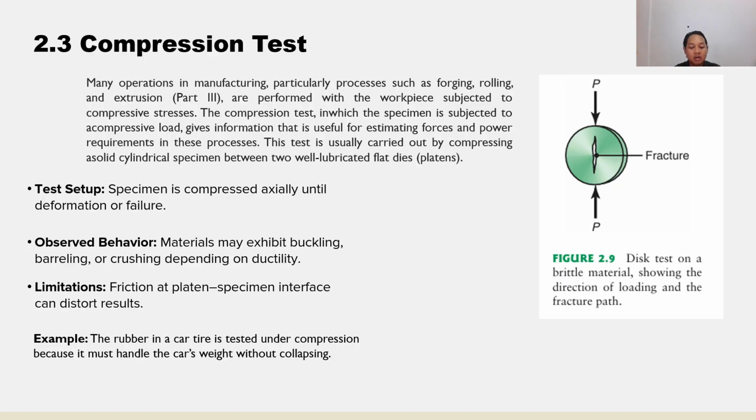The compression test complements the tensile test by studying how materials react under compressive force. A specimen is compressed axially. An engineer observes whether it deforms plastically, buckles, or fractures. An example of the compression test: the rubber in a car tire is tested under compression because it must handle the car's weight without collapsing.